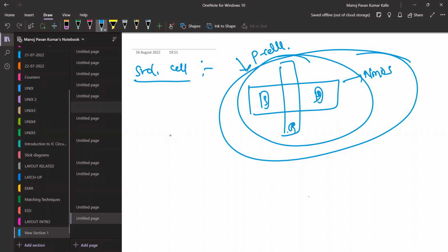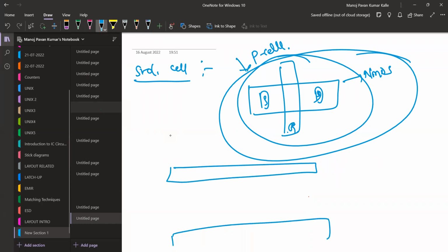Because in standard cells, you have to follow minimum guidelines: all minimum spacings between metal to metal and layer to layer. But in analog layouts, it's not about the minimum spacings. You have to use at least 20% more compared to the minimum guidelines. Let's say the minimum space between metal 1 to metal 1 is 0.1.